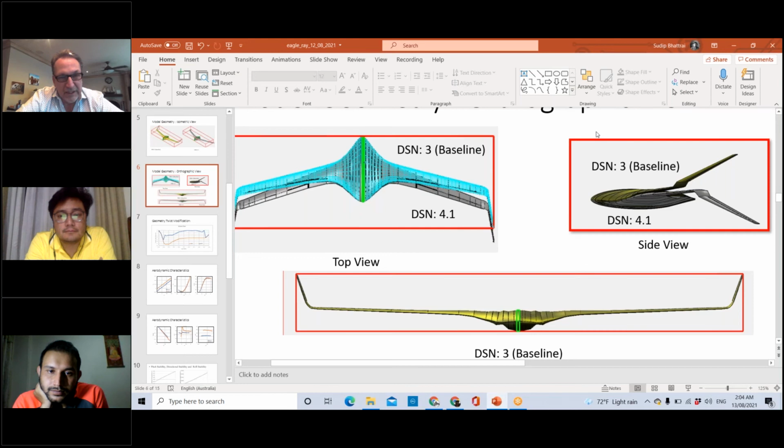We've flown little UAVs with the prop on the nose of a blended wing, and you've got to be really careful. I probably mentioned this before too. The upwash at the nose is a lot, so you might have the thrust line inclined down 20-25 degrees, and it seems crazy, but that's what it wants to be if you have it on the nose. Whereas on the trailing edge, it might be so close to 0. It might look sort of normal. And if you have winglets aiming down and wingtip gear, then you've got all the clearance you need if you want to put the prop in the back. It's kind of a nice package.